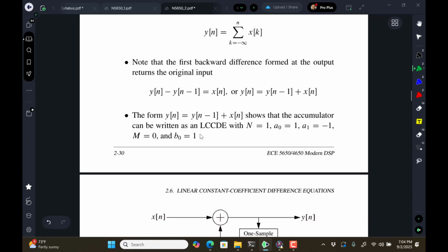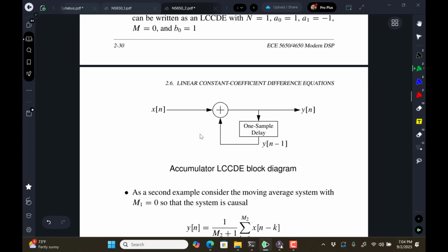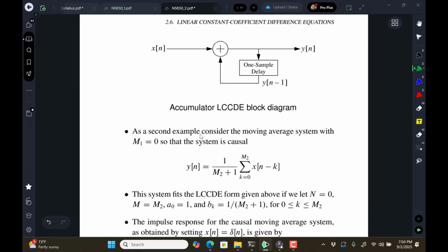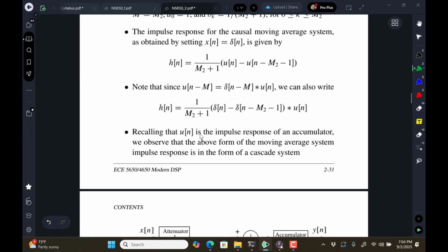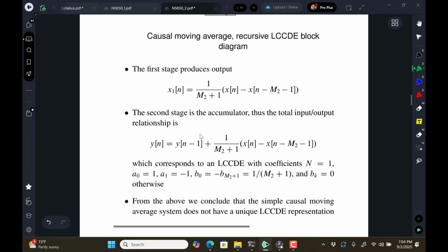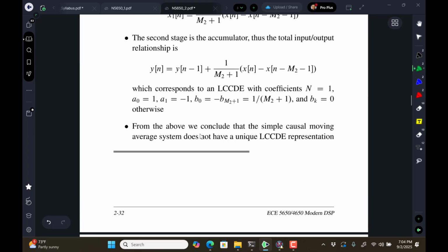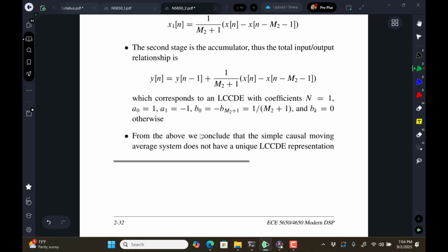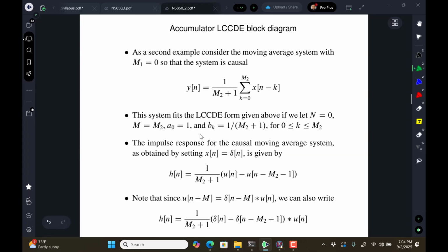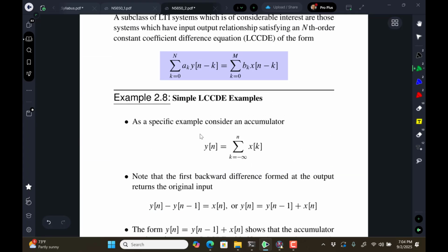But as a practical means, what it really comes down to is the moving average filter we looked at is a difference equation, and we can look at other operations. What we do with the difference equation is, see if I can find an example in here, we rearrange the difference equation. So we have the output in terms of past and present values of the input and past values of the output. So really we're just going up here and rearranging it.